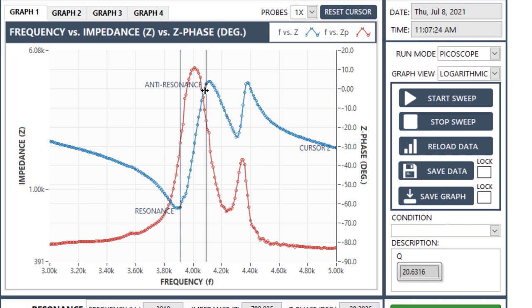Then it's coming back for an antiresonance, and there's a second resonant mode right there. Bending mode actuators are especially susceptible to this, but when this happens in a longitudinal mode actuator, like an ultrasonic cleaner bolt clamp device, this is a big reason for concern. But we'd prefer this not to happen in our bender transverse piezo device, but it does happen.